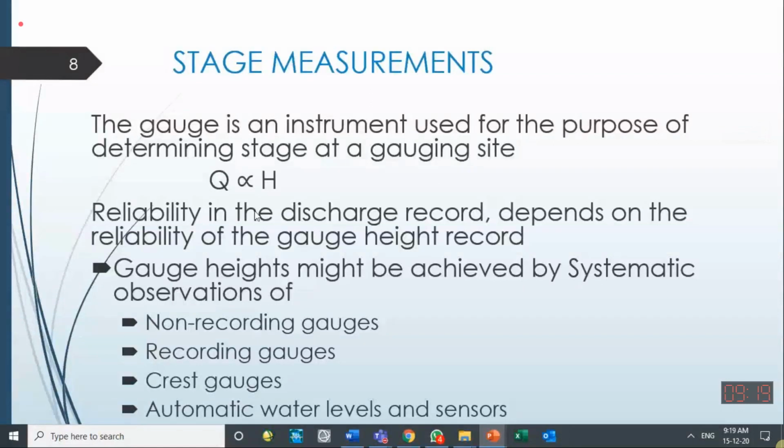At one location, the elevation of water can be 110 meters above the datum, but the depth may be 1 foot or 1 meter above the bed. So both are different things. Depth and elevation you should keep in mind. Usually people mix them. They want to talk about depth, they mention levels. They want to mention levels, they mention the depth. So you should be careful about this.